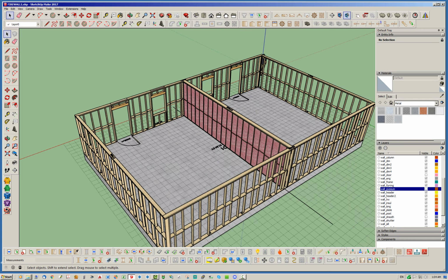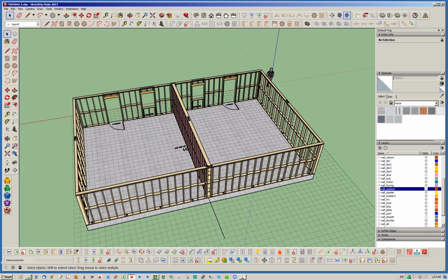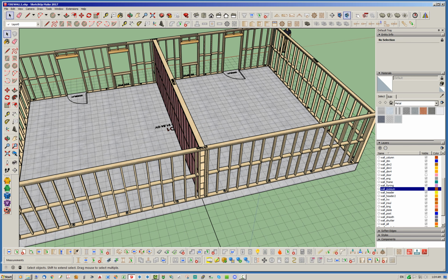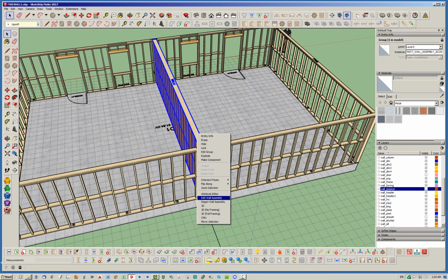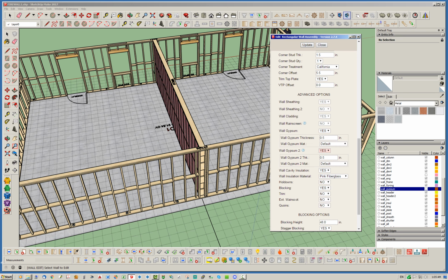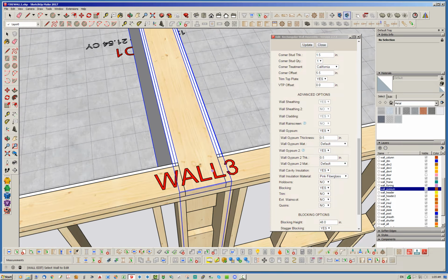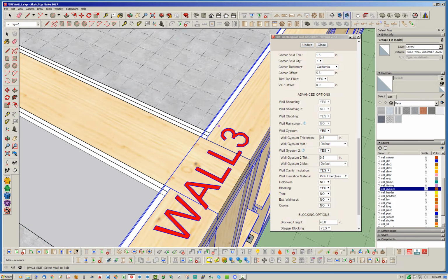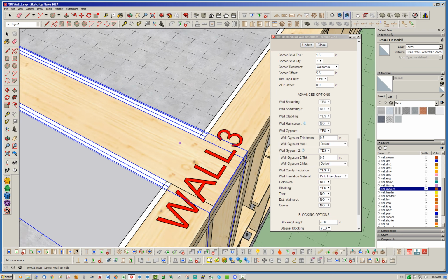With firewall type construction, the only other thing I wanted to point out was that with this particular wall, there are situations, let's go ahead and edit it one more time, where you might want to do a double gypsum wall on both sides. And so you have that option as well. If we turn on our gypsum real quick, I just want to show that. All the other walls are single gypsum, but now we've got double gypsum plus staggered studs plus 2x8 thickness.